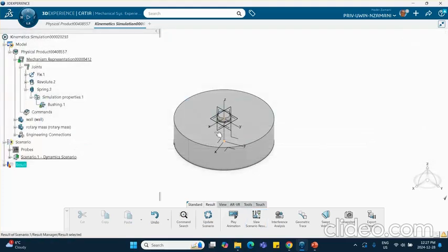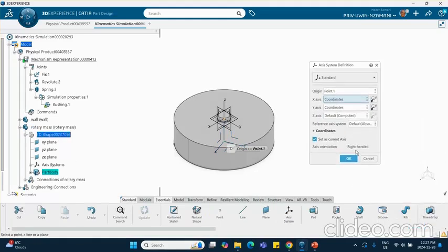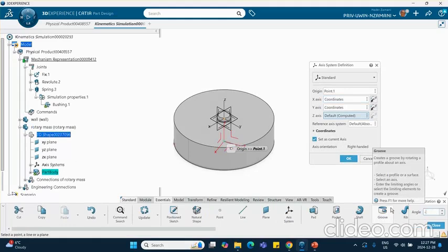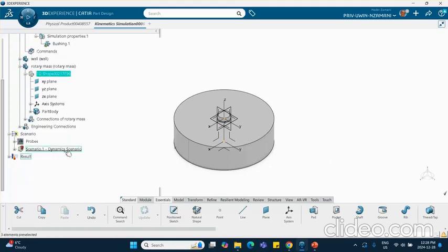Now, what about this 20-degree thingy? Suppose I went and took that 20 degrees away, either for the damped or the undamped case. It really doesn't matter. So I can double click on this. There we are. I'm going to rotate about the Z axis by minus 20 degrees to put it back in the same place, and it aligns it with the wall. Minus 20. Notice that now they're aligned. Say okay. Now we go here and try to run it.